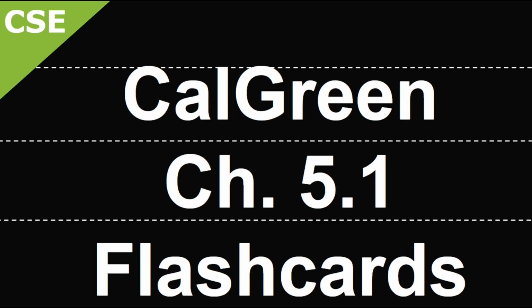The second new update is that if we decide to install a direct current fast charging EVSE, or let's say that another way, if we decide to install a DCFC EVSE, each DCFC EVSE is permitted to reduce the minimum number of required EV-capable spaces without EVSE or EVCS with level 2 EVSE by 5, and reduce proportionally the required electrical load capacity to the service panel or subpanel.